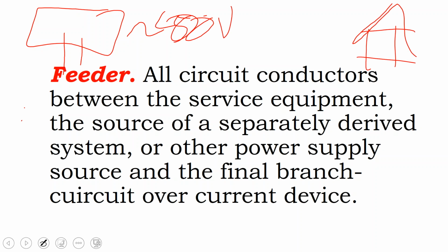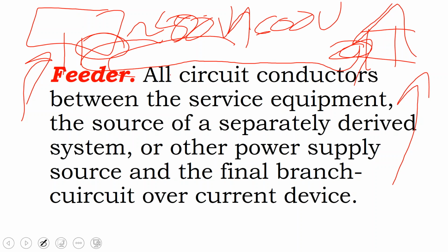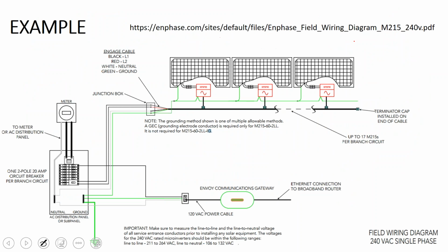Is it better to put your inverter at the solar array, or at the house? Well, what's best is to put the inverter at the house so that you can take advantage of this high voltage run back to your inverter. What might even be better is to use a DC optimizer system to step up the voltage to 600 volts, so that you can push that electricity further across the same cable size. When you increase your voltage, you decrease your amperage. Usually it's the amperage that fills up the cable before the voltage limits get there.